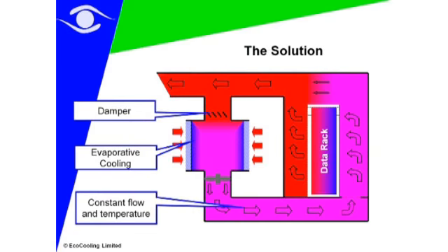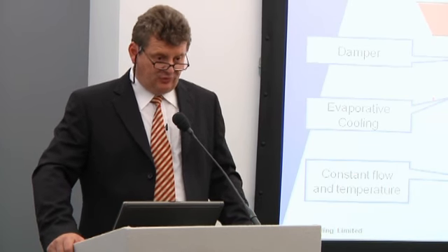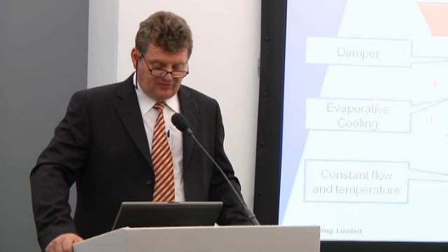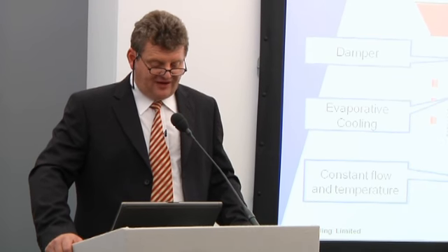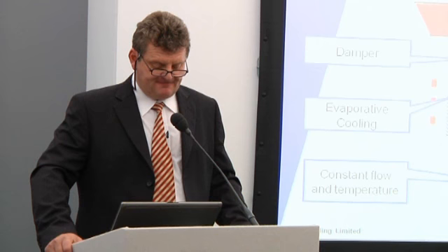This is a cross-section, a simplistic view of how it all works. We have an evaporative cooler, which is providing air through an axial fan, down discharge, and into a raised floor. We then go through the tile, the grill that you see on every conventional raised access floor, going into the cold side of the racks, where the air is pulled in by the fans. It then comes out through the hot side, and then is exhausted out of the building.